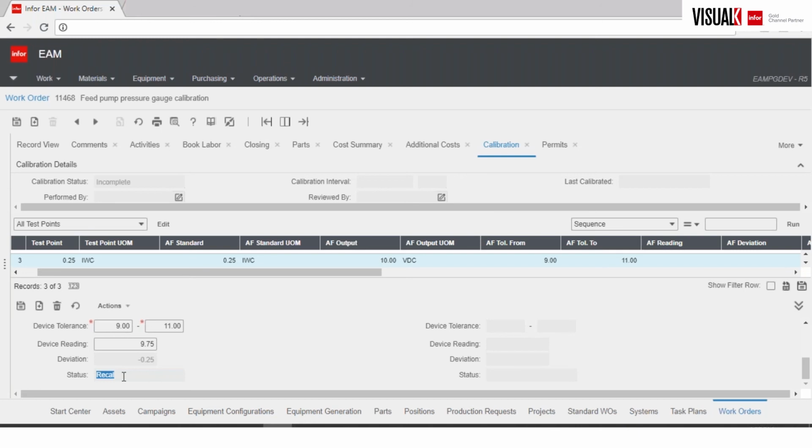So when I discussed my alert tolerance, this is really where it kicks in. What I'm saying is it's within my normal operating range, but the device is drifting. So you can decide whether you want to flag it and say, well, we want to recalibrate this instrument next month or next week, or I can leave it as is, but I have these flags set up.